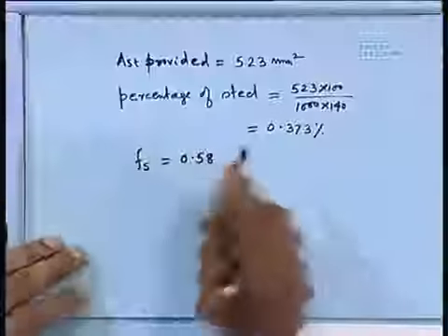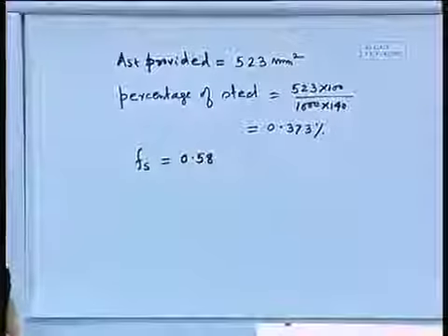If L by D comes less than 25, then we have to change the depth, but if it is more, and we do not consider economy, then we can stop there. Otherwise, if we consider it too much, then obviously you have to reduce the section. So, let us see whatever our code says.